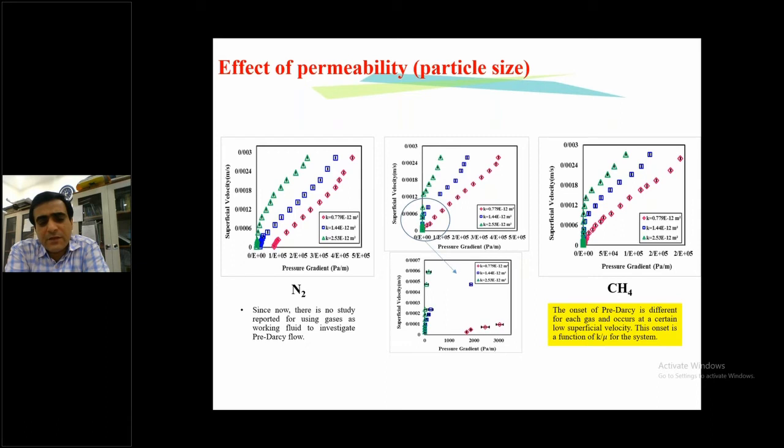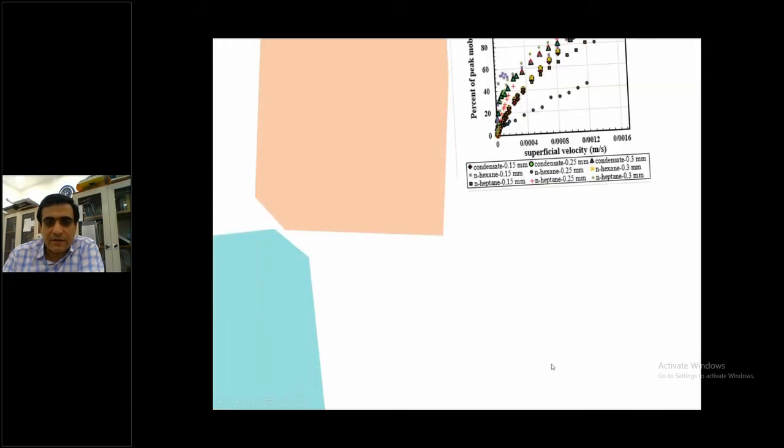It is interesting to see that most reservoir engineers believe that the gas flow is mainly Darcy in the reservoir, and approaches the non-Darcy, I mean the transition flowing conditions, near the wellbore. But we have observed in the laboratory that even for the gas flow, we can expect pre-Darcy flowing conditions. And you can see here the results for nitrogen, methane and carbon dioxide.